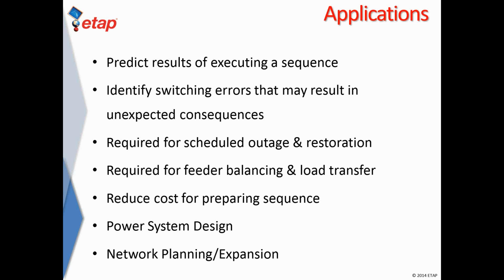And the SSM module is the tool that in essence helps the electrical engineer validate, test, and verify that these switching sequences that are given to the operator will work or behave as expected, right?